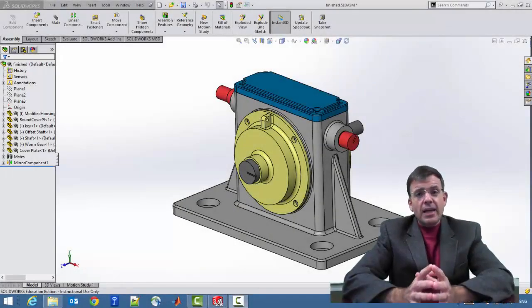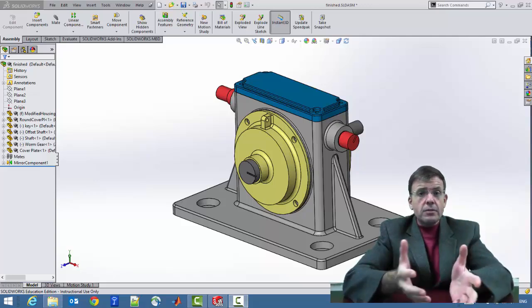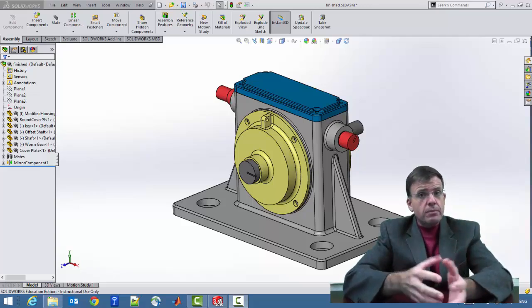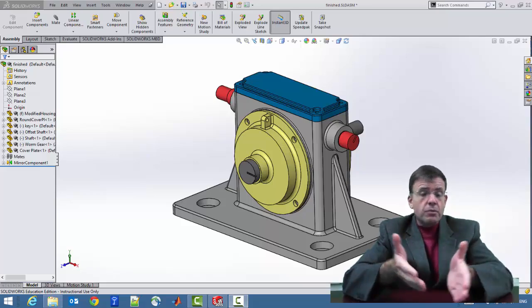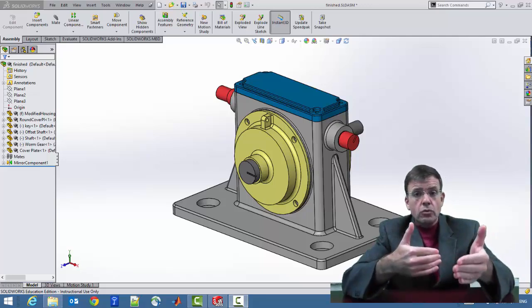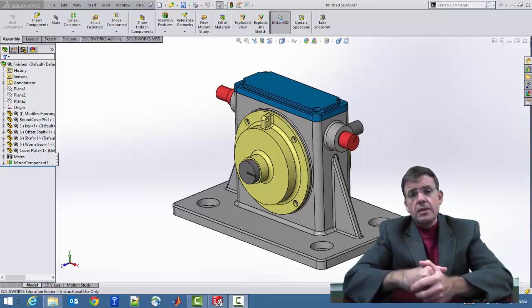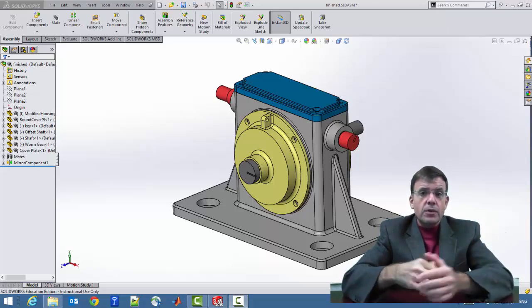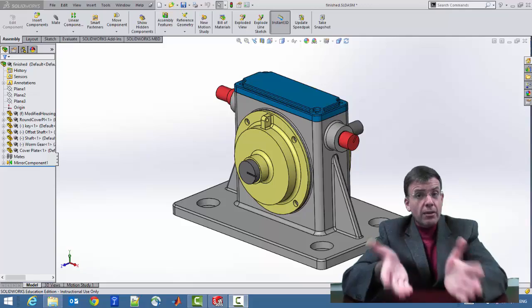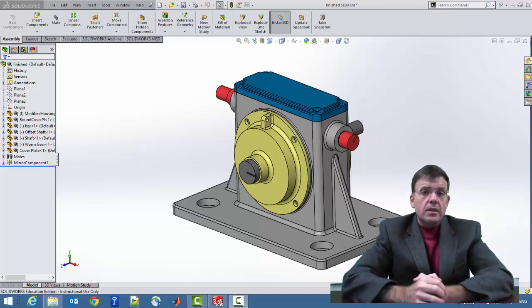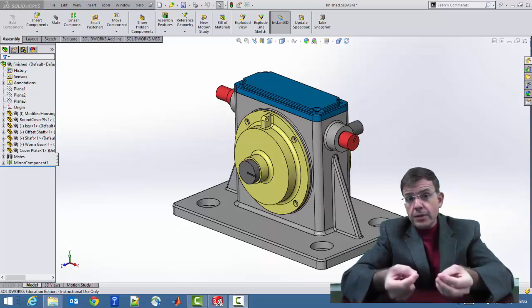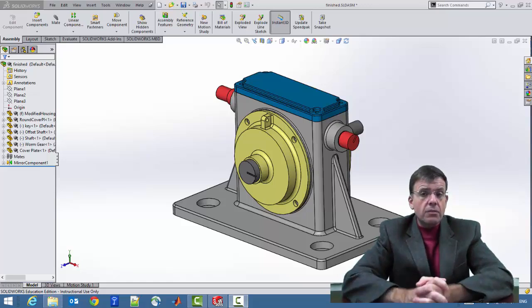Okay, let's look next at the measurement capabilities within SolidWorks. Now, those come in two fundamental flavors. One of them is geometrical in nature. So we're talking about interrogating the model for distances, perhaps between two holes, between two facets or surfaces, between 2 points. We're talking about interrogating for angular measurements between 2 lines, 2 surfaces. Talking about interrogating for perimeters, for surface areas, things of this sort.